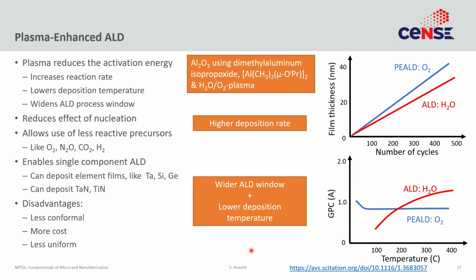One of the ways you can solve nucleation and some other issues is to use plasma. So, this is the relatively new area of plasma enhanced ALD. Equipment to do this has just started becoming available commercially. So, the basic idea is fairly simple. Till now we are doing thermal ALD, which is that all the reaction rates and the mechanism and the chemisorption all assumes thermal energy, right. So, depending on the substrate temperature, things would either happen or not happen.